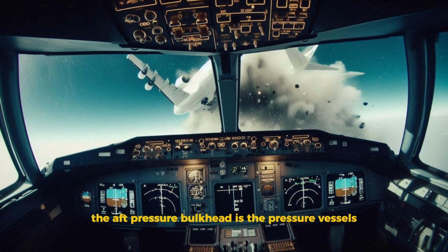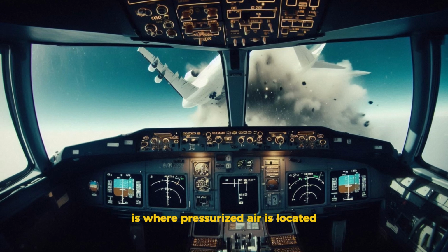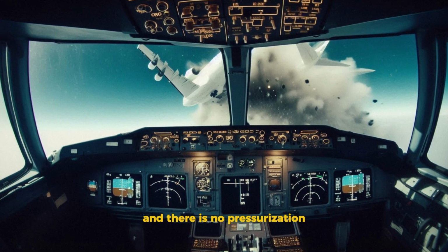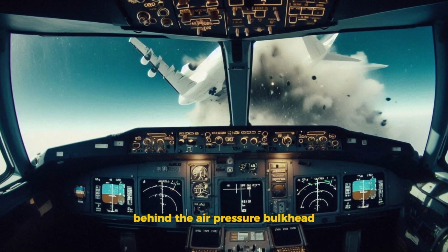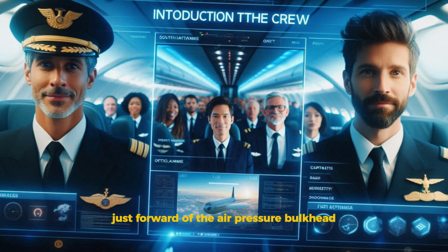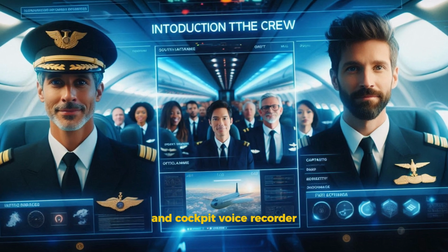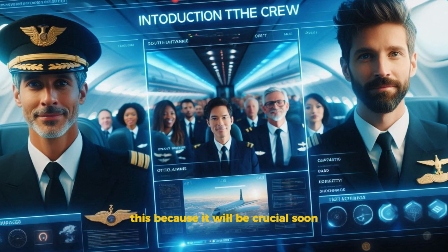The aft pressure bulkhead is the pressure vessel's end plate. The back part of the aircraft is where pressurized air is located, and there is no pressurization behind the aft pressure bulkhead. Just forward of the aft pressure bulkhead, there is a small rack that houses the flight data recorder and cockpit voice recorder. And I'm telling you this because it will be crucial soon.